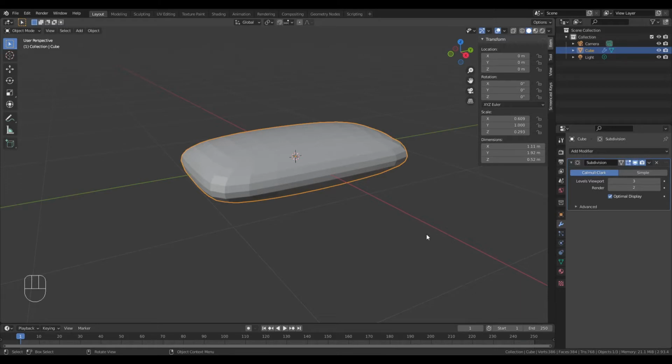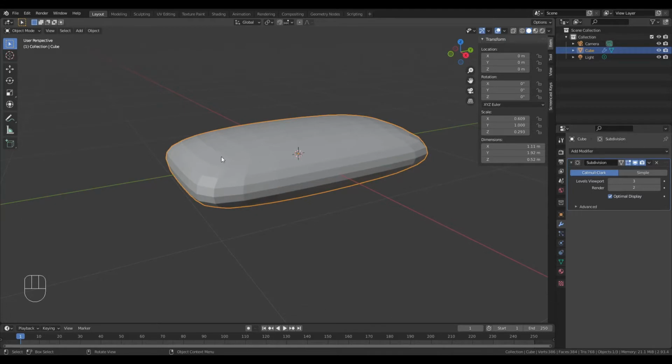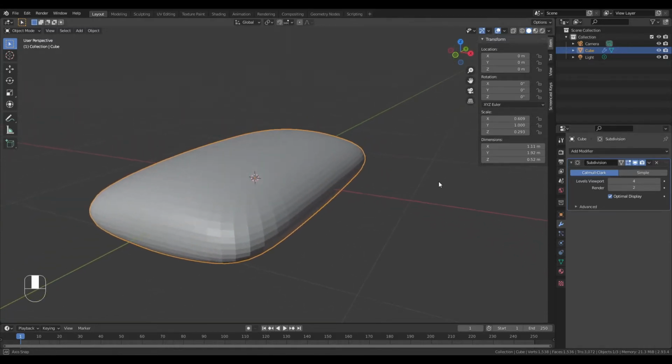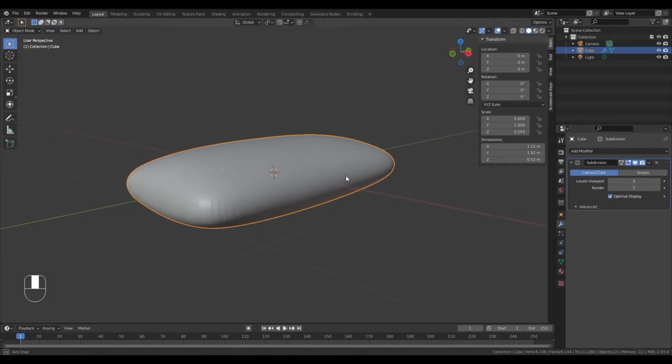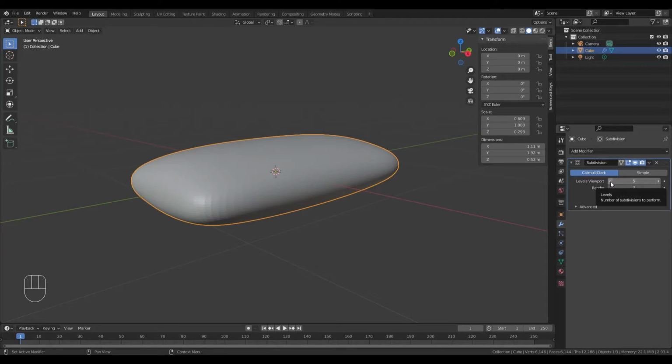So now that we have the basic shape we want, we're going to try to add more detail by doing some very simple sculpting. So sculpting wants a lot of vertex data. So we're actually going to go over to the subdivision modifier. We're going to increase it to, say, 5. And in order to make sure that this works properly for sculpting, we're going to apply this modifier. And once we apply a modifier, it means that we can no longer change these values. So we won't be able to decrease the levels anymore or tweak it by changing the crease data, but that's fine because we're happy with where we're at.